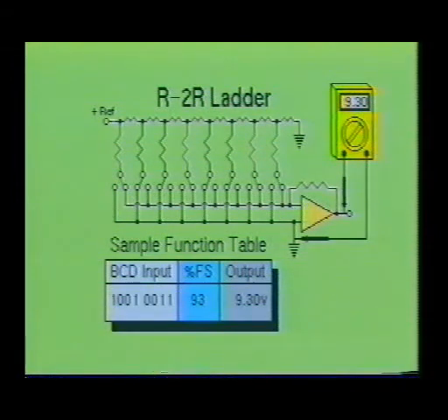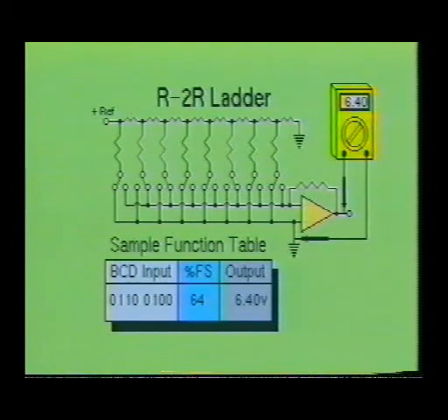The amount of current flowing into the input of the operational amplifier will depend upon the binary word input as well as the feedback current from the feedback resistor. The more current which flows into the input of the op-amp, the higher the output voltage will become. The R2R ladder configuration allows a much higher precision of digital to analog conversion since all the inputs carry comparable currents.